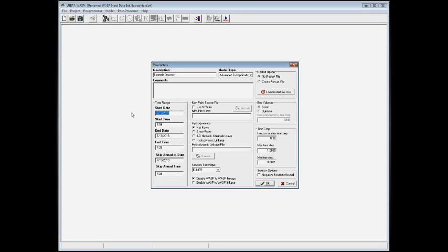If this time is not set, the other icons on the screens will not light up because it does not know what the time frame of your simulation is going to be. So you can see that there's two fields, month, day, year, and then hour, minute. And then I'm going to just put the end time in, so I'm just going to make a 1 year run. So that would pretty much take care of that.